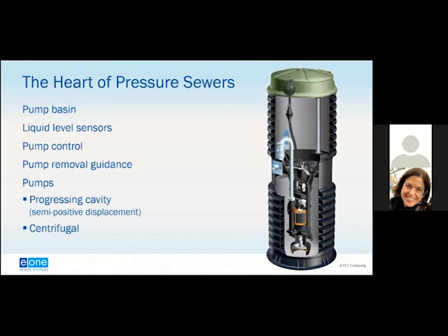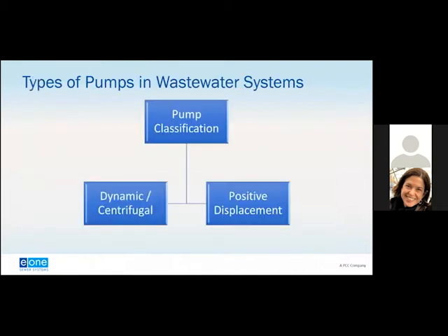And when you're looking at the design and the consideration of a pressure sewer system and what type of pump to use, it is important to really consider everything that would be involved. And that's why the key point of a pump is the curve. That is why my presentation is entitled Avoiding Dangerous Curves with Pressure Sewer Systems, because you want to make sure that the pump curve of the grinder pump is compatible with the pressure sewer system.